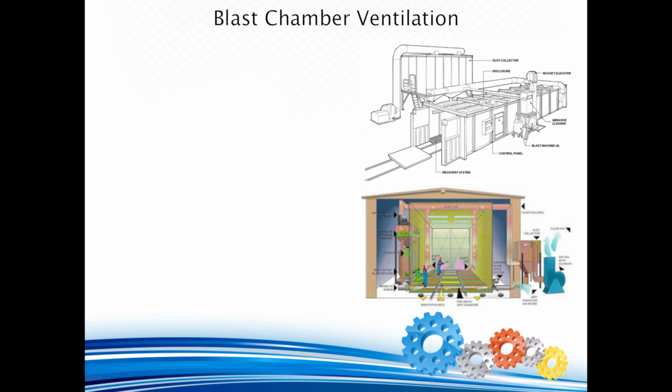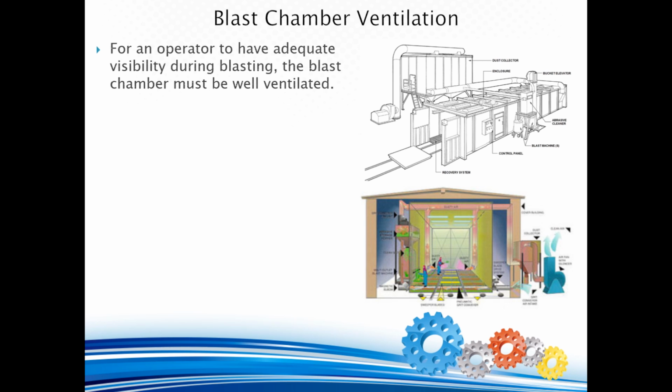Now let's move on to the subject of blast chamber ventilation. For an operator to have adequate visibility during blasting, the blast chamber must be well ventilated. A dust collector should be ducted to the blast chamber at the opposite end of the inlet air plenums to provide the required ventilation air crossflow for removal of airborne dust and fine abrasive media.